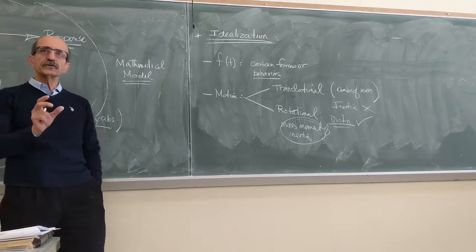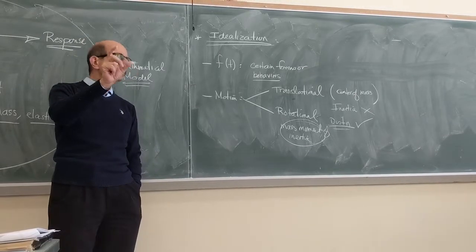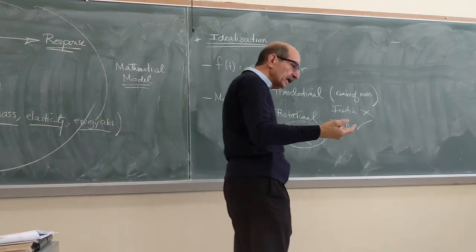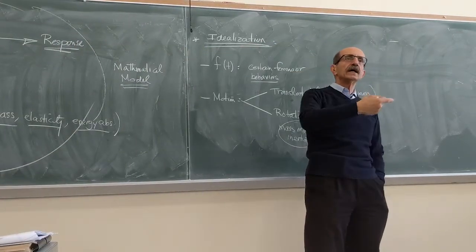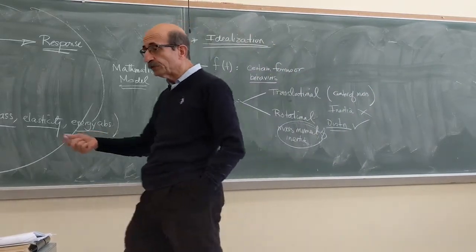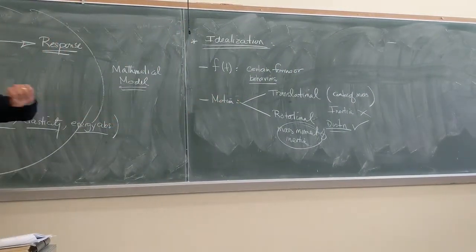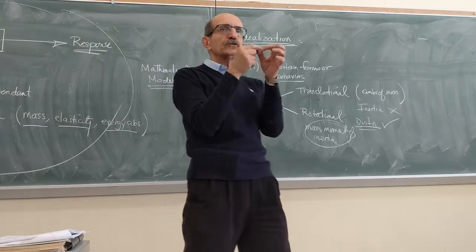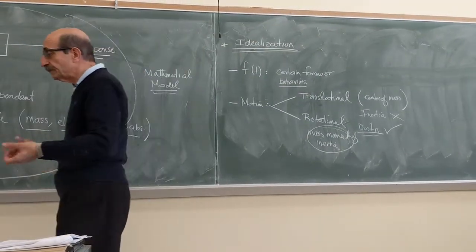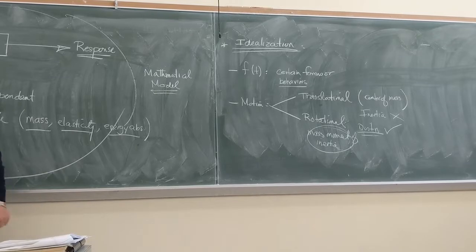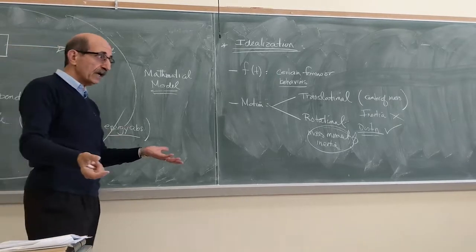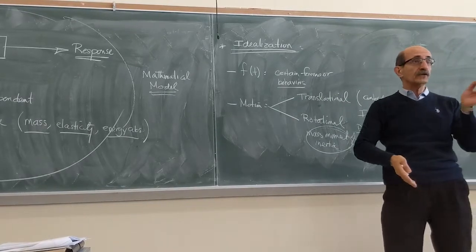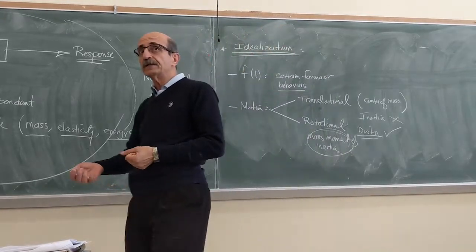In strength of materials, you model the structure very simply: a bar, a shaft, or a beam, depending on what kind of force you had and what kind of deformation you were looking at. If you're looking at just the elongation, compression, or extension, you consider that piece of the structure as a bar. If you're also interested in rotational deformation, you looked at that piece as a shaft. If you're looking at both bending of that element and shearing deformation of it, you look at it as a beam.